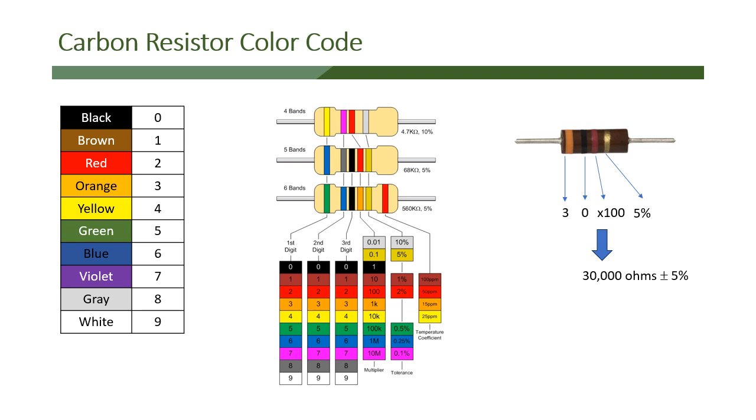So there are 1/8 watt, 1/4 watt, 1/2 watt, 1 watt, and above resistors. And so you want to make sure that you size the circuit so that you do not exceed the wattage capability, the power level of the resistor. And we'll go more into wattage later on in 2B. But just for this point of view, you don't want a resistor that has a wattage level that is less than what your total circuit could be, because it will burn out.